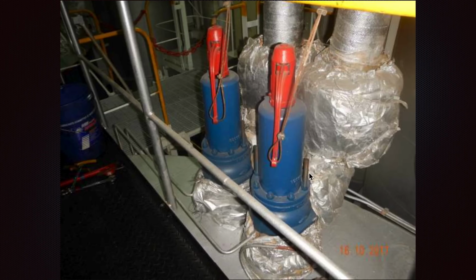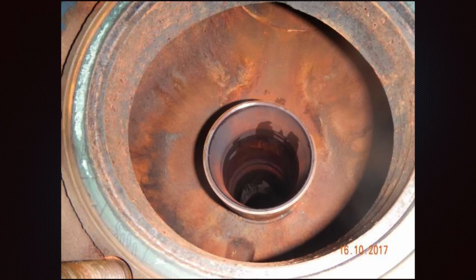Let's move on. Let's see also here, if you would like to dismantle, there are 2 studs here. They are long enough, so when you dismantle one and the other side, it will pull up here and reduce the pressure of the spring. Let's see if we remove the safety valve. This is what we see. Here we have the valve which is seated down, and closes and seals this surface.